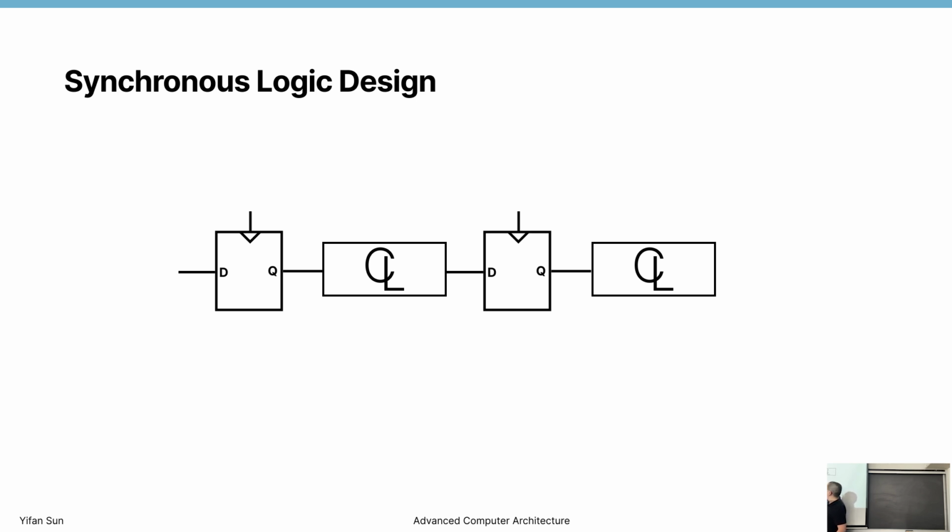Whenever a rising edge arrives, the result is already stabilized and passes from D to N. When the rising edge arrives, N populates to Q and D equals Q for that short moment, then Q will not change for the next cycle. This allows us to do more calculation here, and D will get a new value. There are still some fluctuations and noise, but after a little bit of time it will stabilize, so the data will pass through this register and be put to Q.